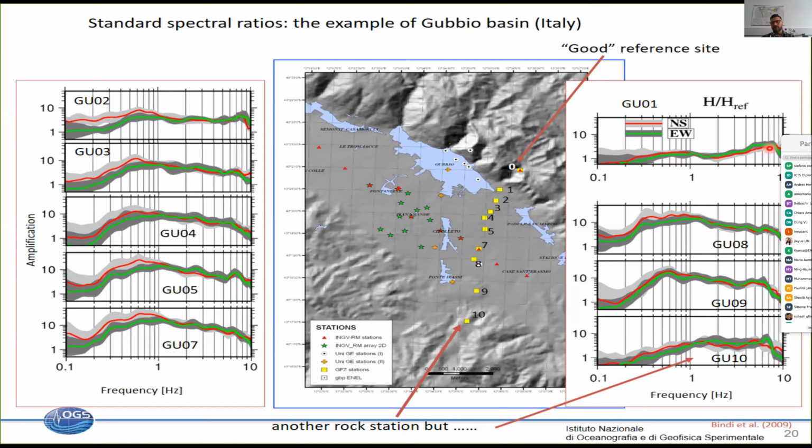So what we observe is that already at station 1, there is some amplification of shaking, mainly around 1 hertz, and then some larger amplification in the high frequency range. This we could explain considering that station 1 is nearby the edge of the valley where we expect that the sediment cover thickness is relatively small.